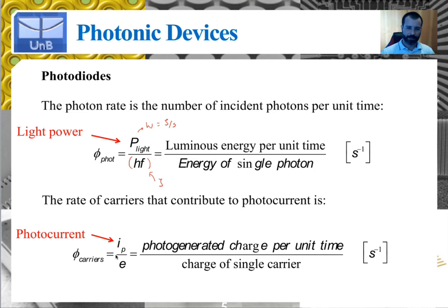Because again, this is given in amps, which is equal to coulombs per second, so charge per unit time. This is the charge of a single electron in coulombs, and therefore if we divide this, which is the charge per unit time crossing the cross-sectional area of a wire, by the charge of a single electron, we find the number of carriers, the number of electrons and holes which are crossing the cross-sectional area of the wire or the semiconductor per unit time.